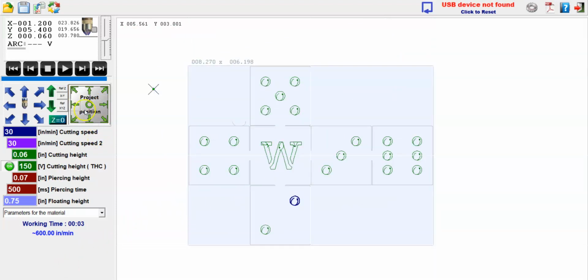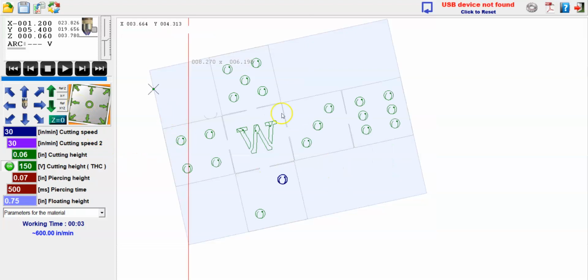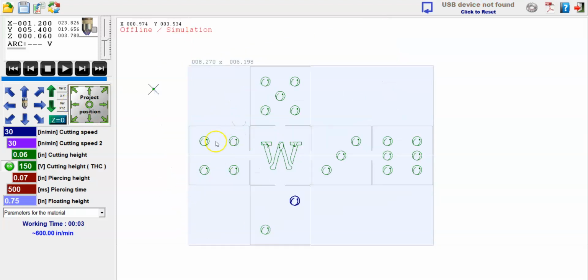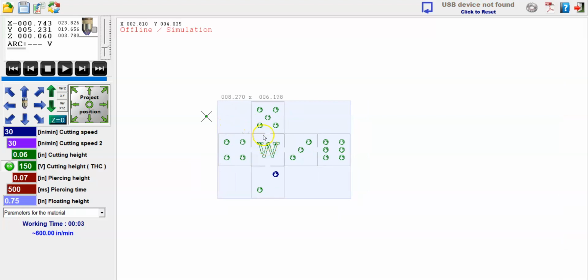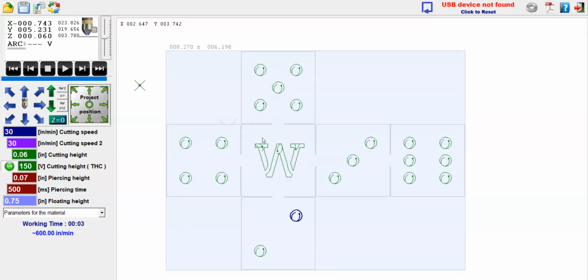Oh, I almost forgot to mention, that's probably something important here. So once you have your material off, bent this way, sometimes you need to get back to reality, snap off of this material, because it won't do anything else if you're still locked in this position. So after you've made your cut at this angle, you need to go back. All you have to do is right click again, and it will place everything back to normal. You can actually work on everything on your screen here. So just keep that in mind, and we're going to get into bringing a part in.